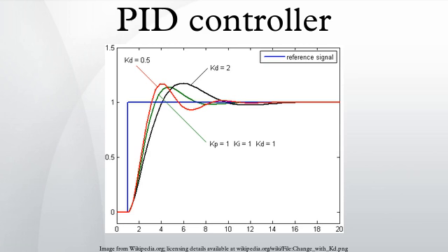The inner PID controller controls the temperature of the heater using a thermocouple attached to the heater. The inner controller's error term is the difference between this heater temperature setpoint and the measured temperature of the heater. Its output controls the actual heater to stay near this set point. The proportional, integral and differential terms of the two controllers will be very different. The outer PID controller has a long time constant: all the water in the tank needs to heat up or cool down. The inner loop responds much more quickly. Each controller can be tuned to match the physics of the system it controls, heat transfer and thermal mass of the whole tank or of just the heater, giving better total response.